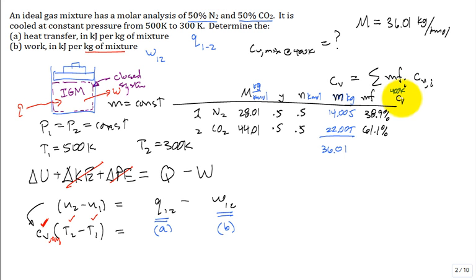That's our average temperature for the process. It's going to have units of kilojoules per kilogram Kelvin. And we then read out those C sub V values, 0.747 and 0.750. Not very different, is it? Not very different.